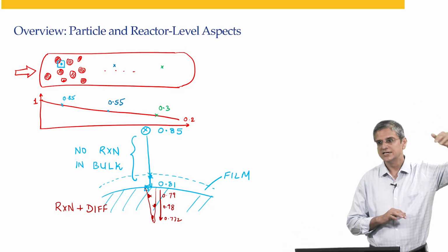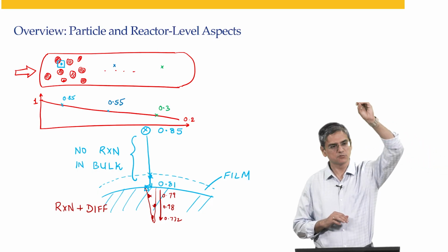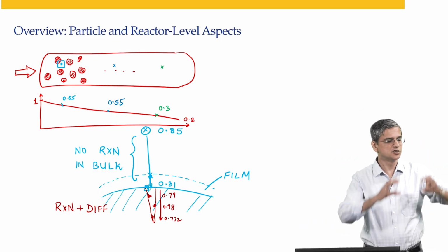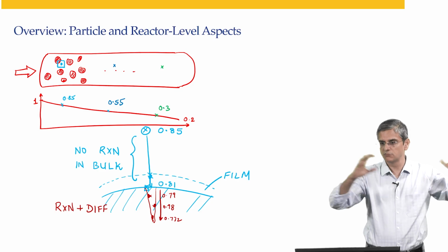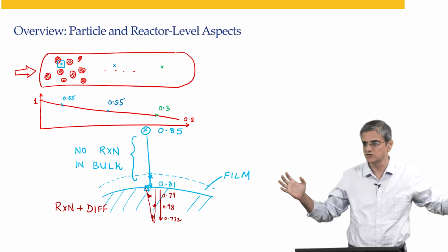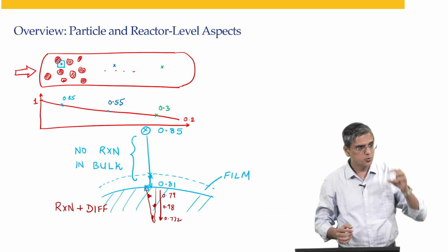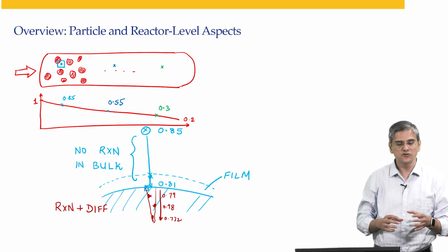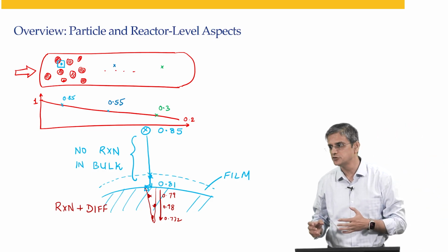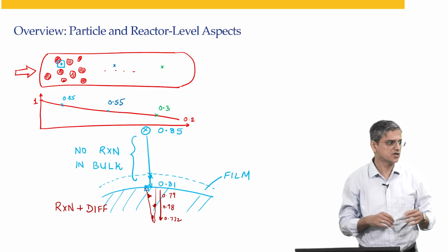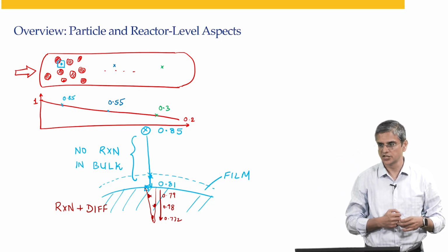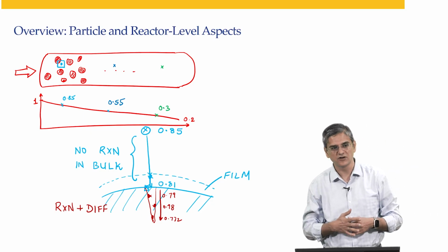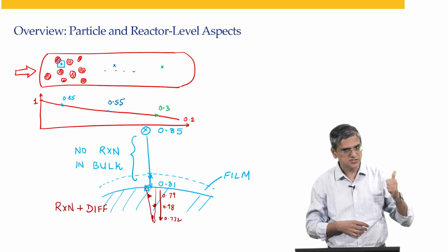Difference number one is external diffusion is completely a molecular diffusion. You have the molecule just diffusing in rest of the gas or rest of liquid. Within the pore, there is a pore diffusion. A pore diffusion is affected by both molecular diffusion as well as something called Knudsen diffusion. We will come to that when we start module 5b. So that is difference number one.